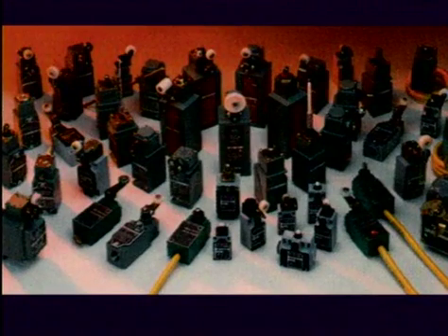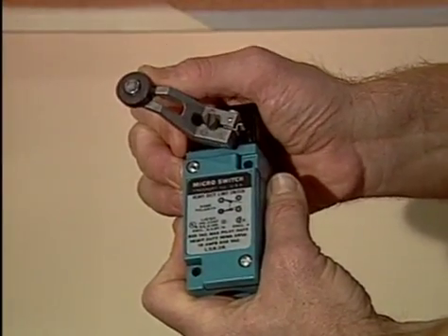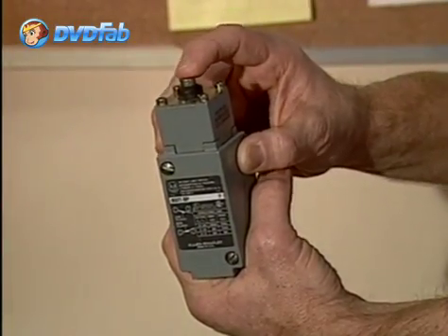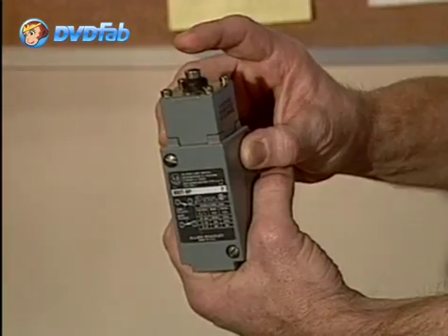There are many types of limit switches, and depending on the application, the proper type must be selected to obtain the desired control. All of them, however, have the same basic operational characteristics. Let's first start by reviewing their construction and the components that form them. Limit switches are composed of basically two parts: the actuator and the electrical contacts. The actuator comprises a lever that provides an actuating mechanism to close the contacts of the switch. In other words, the actuator is the sensing part of the limit switch, which translates the detection into an electrical control signal at the contact assembly, as we'll see shortly.